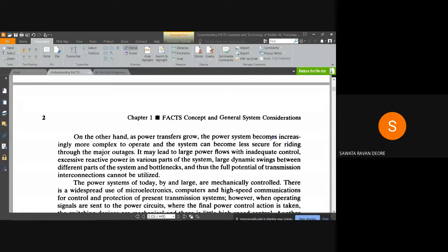Flexible AC transmission system is if we have some fast controller connected to that line, which will increase the impedance of that line so that the power flow through it will be limited and automatically diverted to the other parallel path available in the network. So that is the opportunity for FACTS devices in such cases.